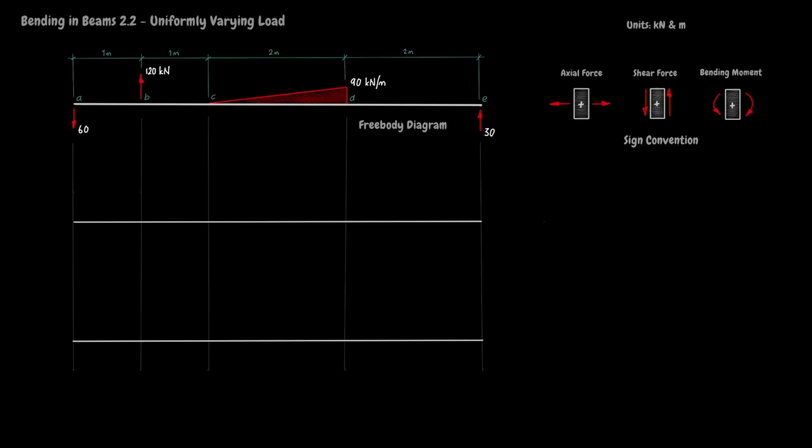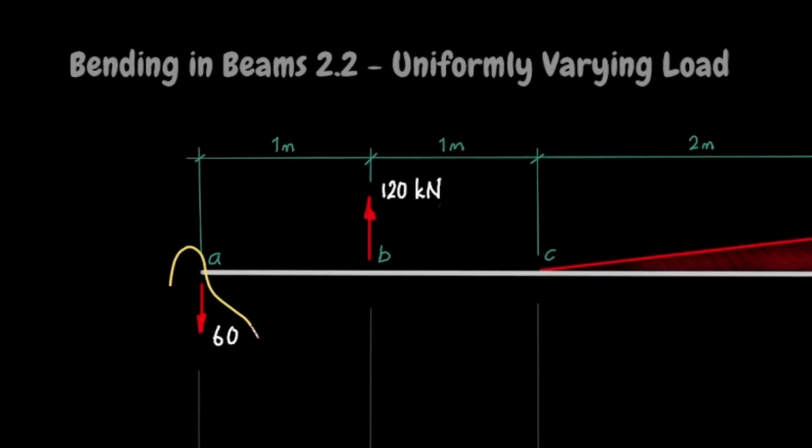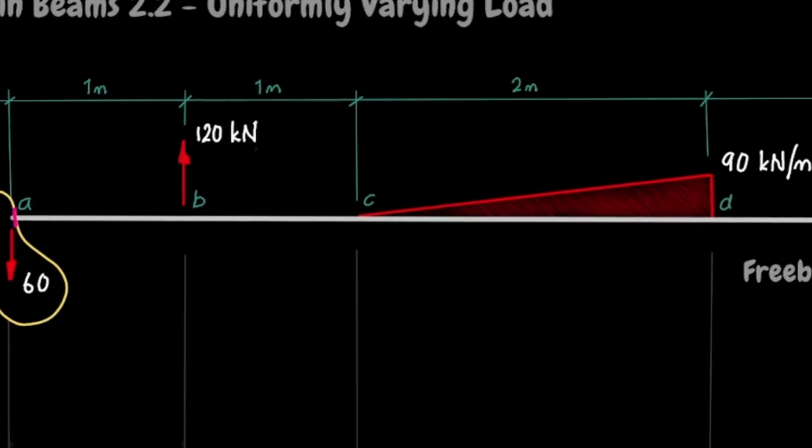We will work left to right along the beam, calculating internal forces in the beam. To do this, we must cut the beam to expose the internal forces, so start by drawing a free body diagram bubble that cuts the beam just to the right of A. Now draw the free body defined by the bubble and label the unknown forces exposed by the cut.